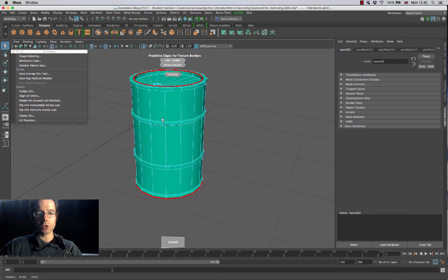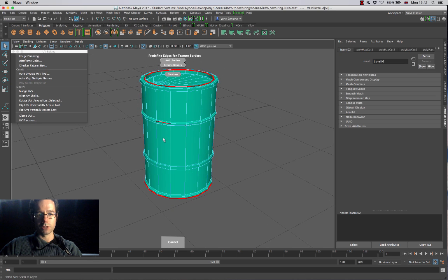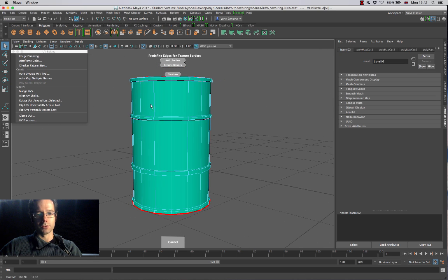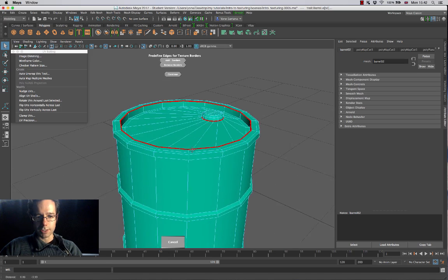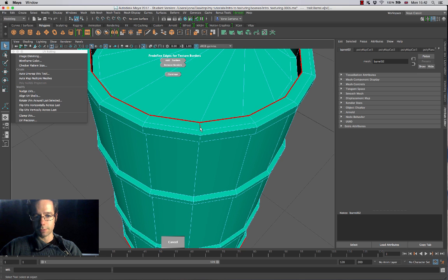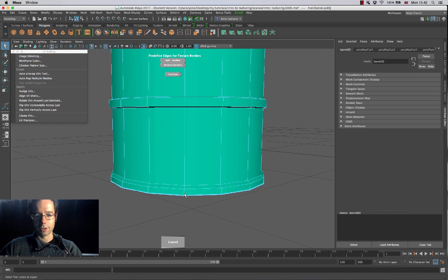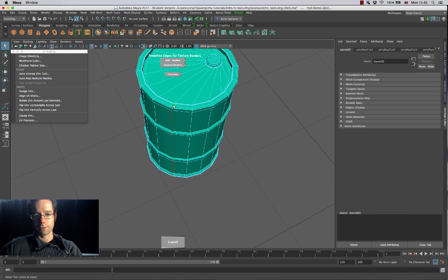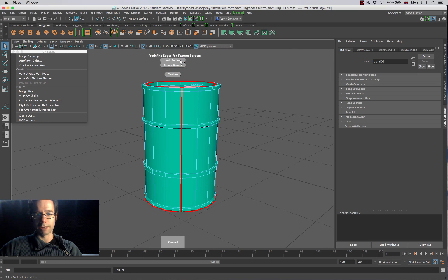And then we have to choose where along the height we're going to do our seam. So if I wanted my object to be seen from here, maybe I'll add a seam around the back over here. And thanks to Maya's selection tools, this can be very easy, because I'm just going to zoom in to this area next to where that edge is, click on the first edge over here, and then go all the way down and shift and double click at the end over here. So Maya will make a selection from my first edge to the end selection over there, and it creates a perfect line just like that following the geometry. And I'll add my last border there.